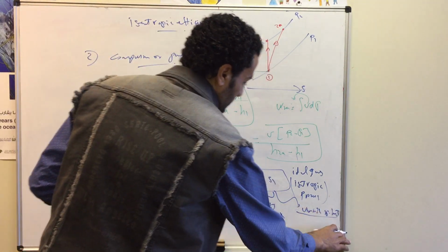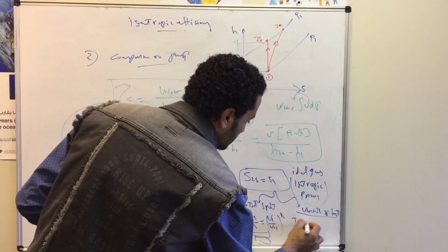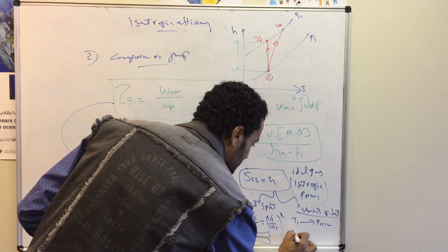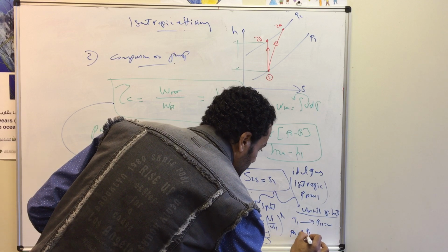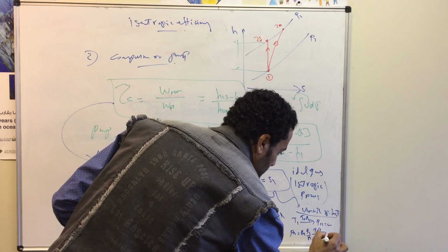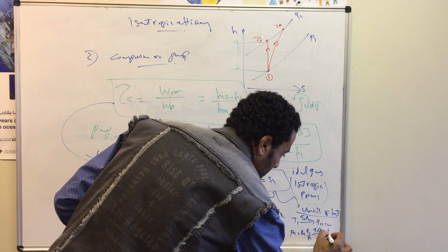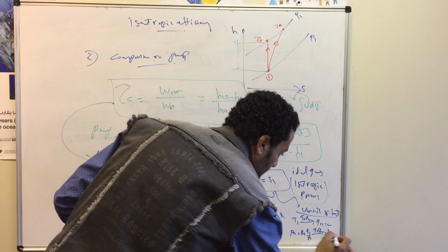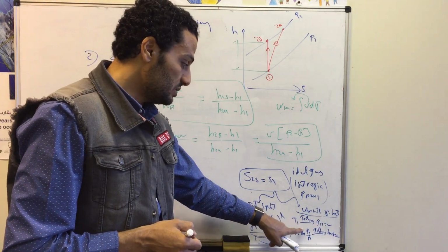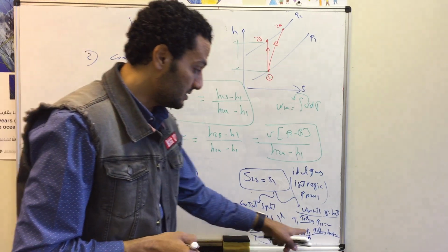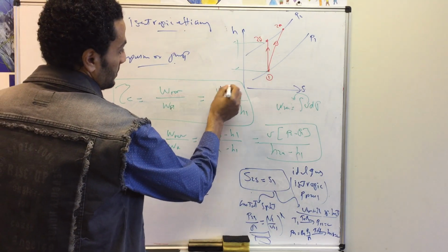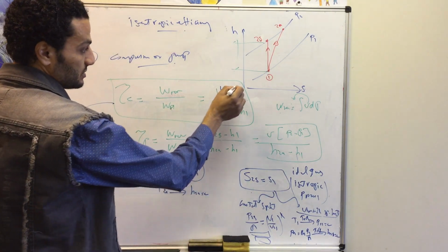Or using the variable specific heat analysis, at temperature T1 we can go to the table and calculate, let's say, Pr1, and then Pr2 is equal to Pr1 multiplied by P2 over P1, and then go to the table again and calculate h2s. So it will be: at temperature T1, calculate Pr1, then calculate Pr2, which is Pr1 multiplied by P2 over P1, then go to the table and get the value of h2s. So we can substitute here by h2s, and now at temperature T1 we can just go to the table.